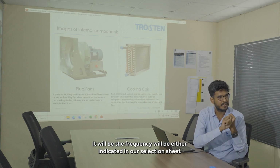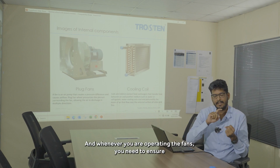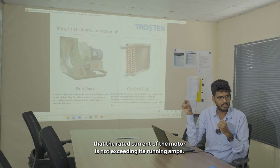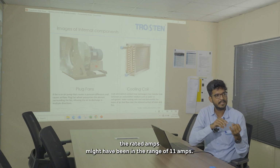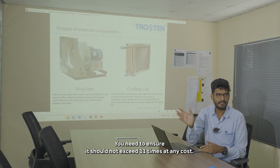condition. Okay, the frequency will be indicated either in our selection sheet or in the unit nameplate itself. And whenever you are operating the fans, you need to ensure that the running current of the motor does not exceed its rated amps. For example, if the motor capacity is 5.5 kilowatt, the rated amps might be in the range of 11 amps. You need to ensure it does not exceed 11 amps at any cost.